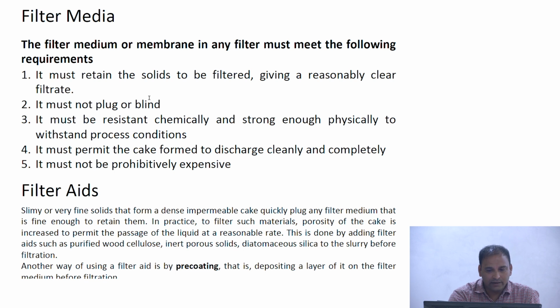And of course, it should be chemically resistant. It should be physically strong as well, to withstand whatever operating conditions you are dealing with. You may be doing filtration at high temperature with a higher pressure differential, so it should be able to withstand all these operating conditions.